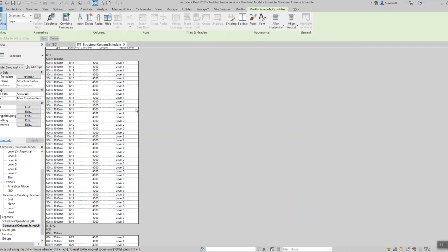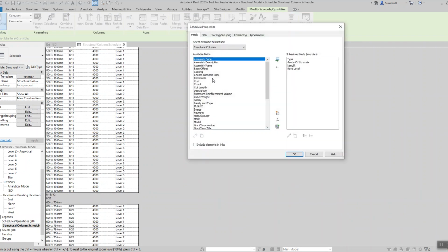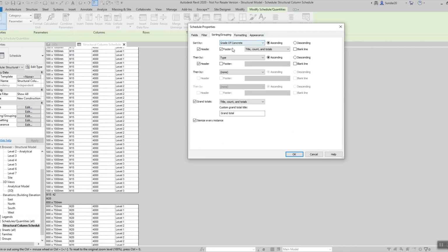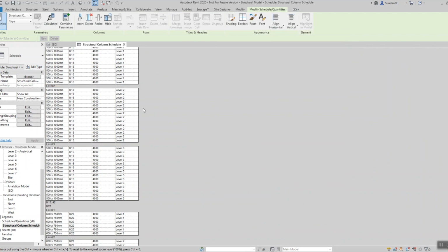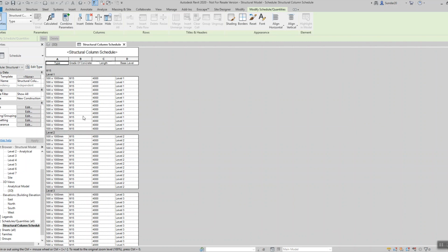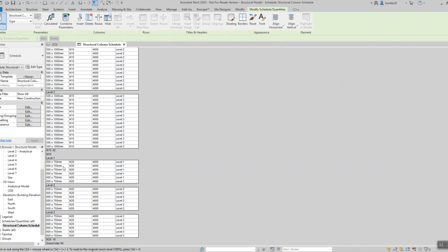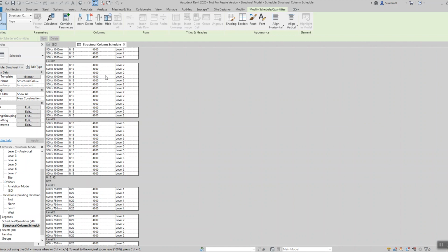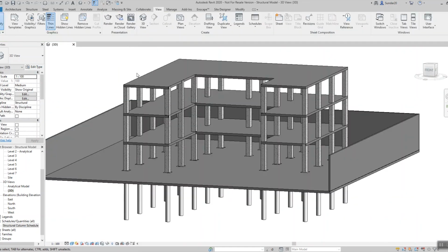So level 1, level 2, level 3, based on that, in that also you are able to filter it out. Mostly you'll be using these options on a daily basis. Revit users generally will be doing this. So type-wise, base level-wise, it is segregated by the categories and as well the levels. By this way you can add a parameter to a component using a project parameter. Using project parameter, you can add these things.